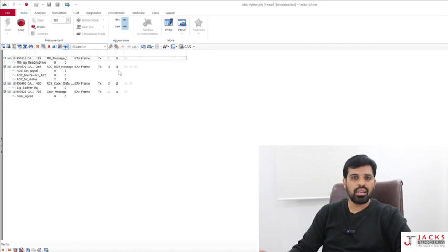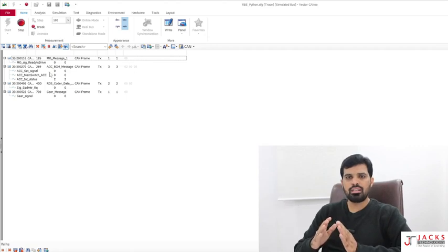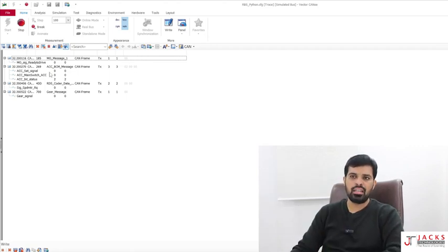Using rest bus simulation. Who created this rest bus simulation? The test engineers will create this rest bus simulation by using the CAPL script. Now through rest bus simulation, the messages are getting transmitted over the CAN with default values.